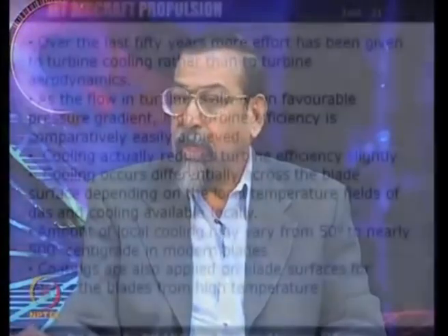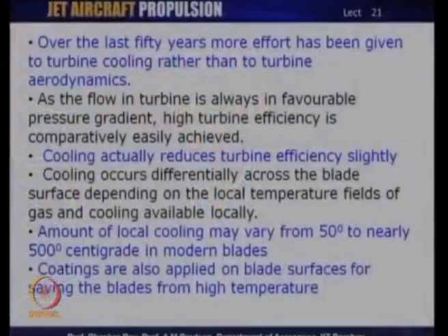Over the last 50 years, if you see, more and more effort has been given to turbine cooling rather than to turbine aerodynamic design. And as the flow in turbine is always in favorable pressure gradient, high turbine efficiency is comparatively easily achieved. However, more work done requires more temperature, and that is why more effort has been given to raising the temperature. The cooling actually reduces the turbine efficiency slightly, but that is a penalty that you pay for getting more and more work out of the turbine.